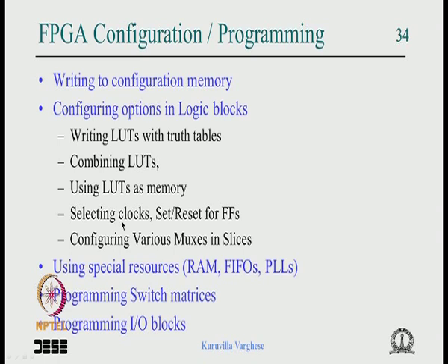To the flip flop you can select the number of clocks, maybe more than in CPLDs. You can do the set and reset of flip flops, and there are a lot of multiplexers within the logic block to make it flexible with various programmability, and all that is programmed. These mux paths are programmed by writing to configuration memory.